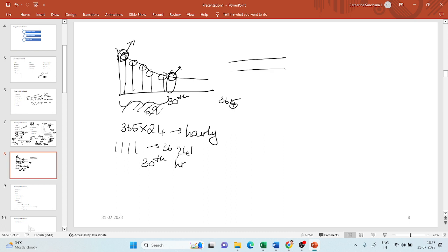I'm going to design this pavement for this traffic which will act on this pavement only for 1 hour, which is not economical, right? So I'm going to say that for 29 hours in a year, the traffic on this road can exceed the traffic for which I have constructed the pavement. For the remaining hours, my road will be able to take care of the traffic that is coming onto the pavement. So that is the 30th hourly volume concept. Okay.